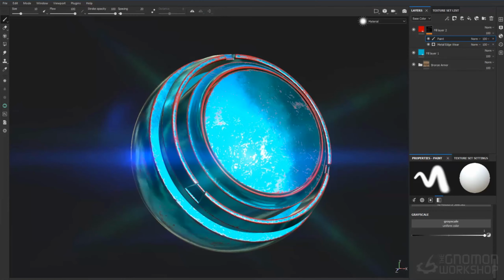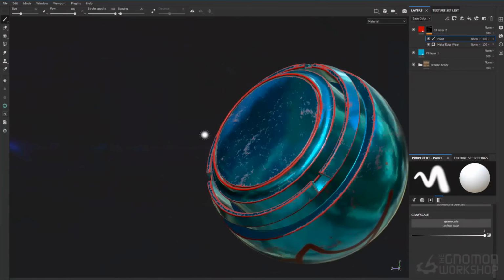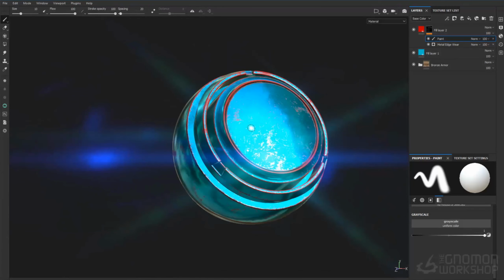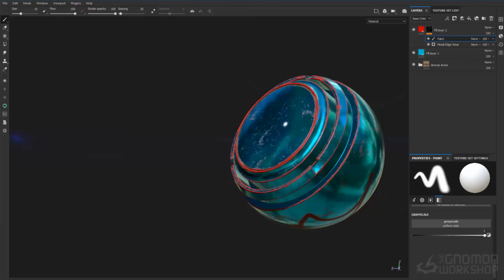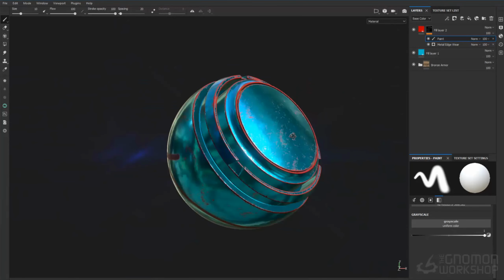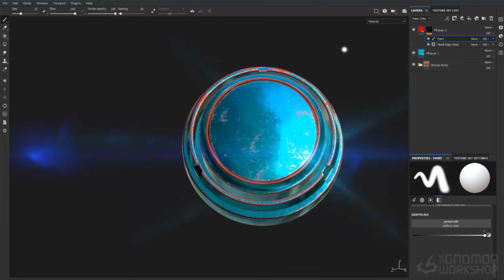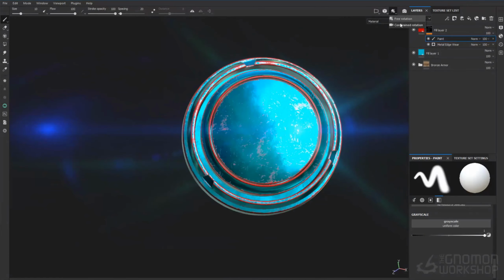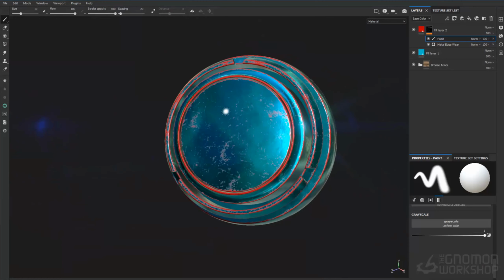So the next thing we want to look into is perspective view and orthographic view. Orthographic is going to be flat. Because that object is not perfectly aligned, it's not going to work. But what you can do is Shift Alt, left mouse button, which allows you to rotate your camera 90 degrees. Perfect 90 degrees. So perspective view, and I can rotate 90 degrees all the time, but my object is not perfectly aligned in the world anyway. And since we are on the camera, you get free rotation and constant rotation. Free rotation, basically wherever I click in the world is going to be the pivot point for my camera. Constant rotation is the center of my object or center of my scene.